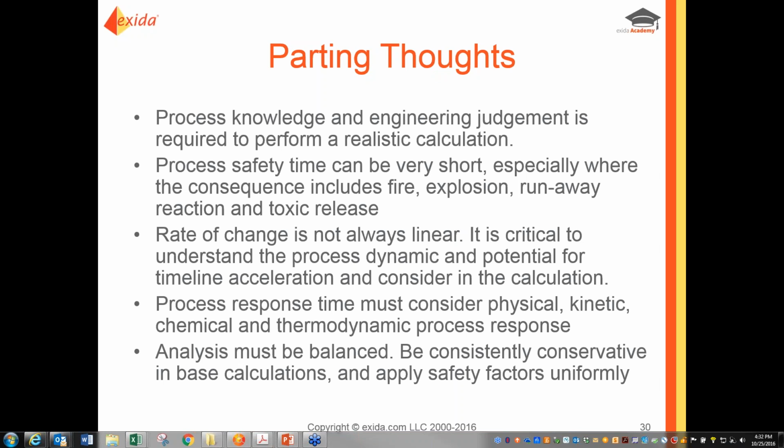How is this typically accomplished on a new process? Again, working with the process engineers. If you've got a contractor that is doing the design, or if you've got computer modeling, if there's an Aspen model of the process, that's a great opportunity to make it part of your early engineering design and help set your SIF trip points. Depending on what you find as you're doing this analysis early enough, you may want to go back and change something about the process, physically go with an inherently safer design option in order to adjust these timelines as well.